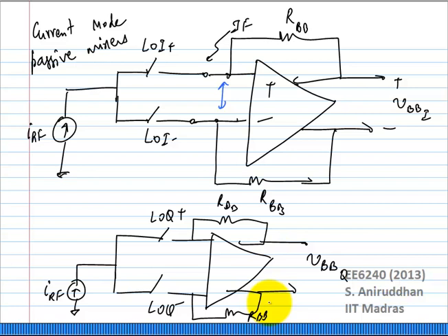So first of all, because you are dealing with current, all these nodes are very low impedance nodes and therefore very broadband nodes. Okay, so if you are really interested in a very broadband signal, or if you are interested in a multi-band system, you can use the same mixer and baseband to actually process multiple RF bands.